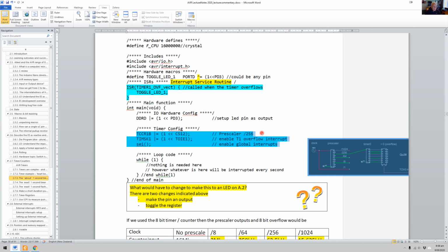So what's going to happen now, and this is shown in the Pactorial video as well, is it's just going to tick over and change our LED state from 0 to 1, 1 to 0, every second. Not every half second, every second it's going to toggle it. So 1 second on, 1 second off, or approximately. It's 1.04. Remember that this is an approximate count. We'll get into those more juicy details of timers later.